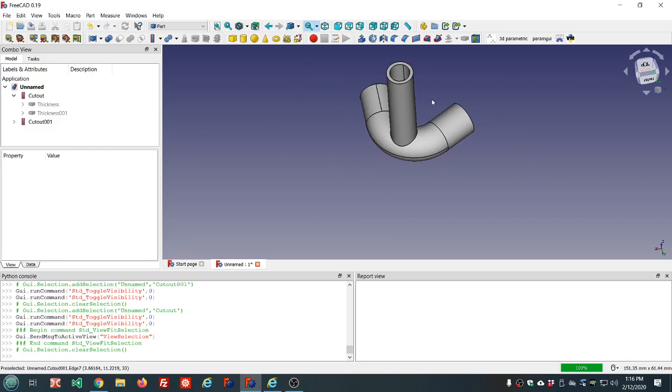Well, that's going to be it for today. We have covered using the torus. We've covered attaching objects to other objects. Attaching is something that you would probably use quite often, especially when we get to sketching and using the sketcher, which is a really fun tool to use in FreeCAD. When we get to the Part Design workbench, which we'll cover after we finish with Part, that's a sketch-based modeling style. The modeling style in the Part workbench is we begin with ready-made geometries and combine them with Boolean operations. We can also do sketch-based modeling in Part, and we will do that in the Part workbench.